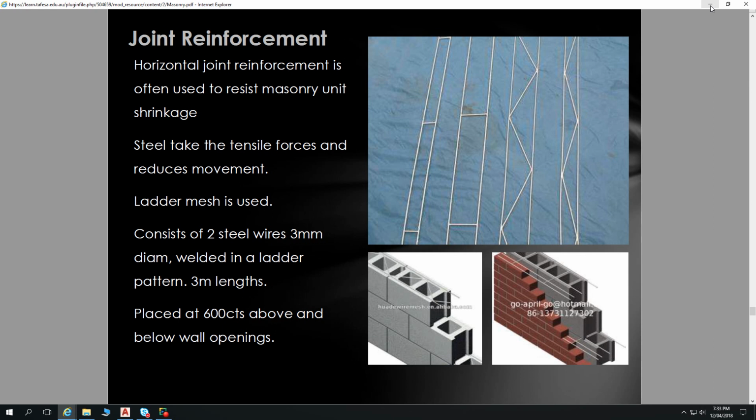With concrete blocks, if they're relatively fresh and haven't been sitting around for a while, you get shrinkage of the concrete blocks along with the shrinkage of the mortar. So that can certainly be an issue. I saw it as a significant issue in a house. I was doing a final progress inspection of that house, and I had control joints about this wide in there. So we saw our control joints before, how we've got that foam backing in there. Sometimes it's done with a long skinny foam, and that was all just going like this in the joints.